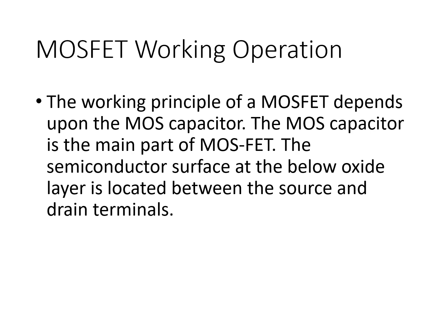When we apply positive gate voltage, the holes present under the oxide layer experience a repulsive force, and the holes are pushed downwards into the substrate. The depletion region is populated by bound negative charges that are associated with the acceptor atoms. The electrons reach and the channel is formed. The positive voltage also attracts electrons from the N source and drain regions into the channel.